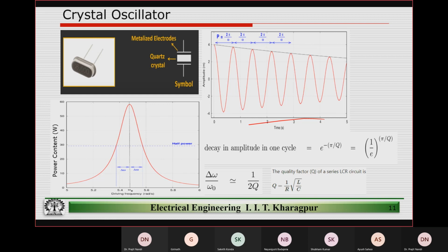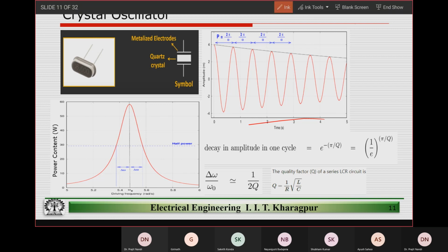So there are actually other definitions of Q, all coming from the same math. I'm not going to get into more definitions of Q, but another thing, right? This is a question actually. Let's say you're designing an amplifier, and the amplifier, let's say, is a second order system, right? And for that second order system, what do we write as the second order system? S square plus 2 zeta omega n s plus omega n square, something like that we write, and there is a DC gain, right?